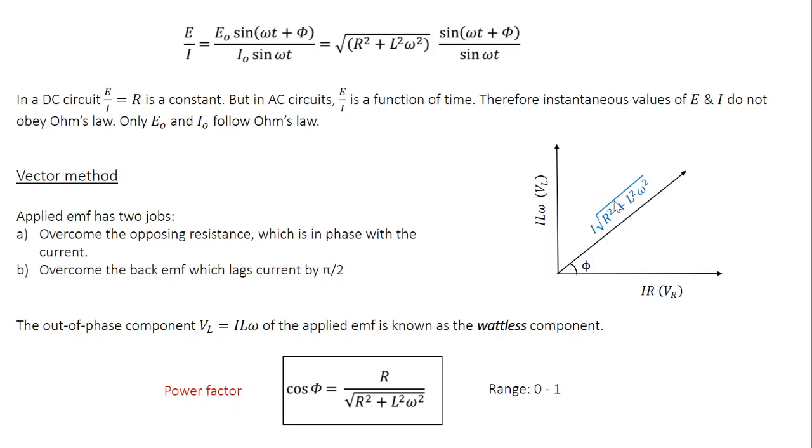Also, in the previous class, when we discussed AC flow through an inductor, I said that if you look at the waveform and analyze successive quarter cycles, you will see that in one quarter cycle power is positive and in the next quarter cycle power is negative. So the power is continuously transferred between the source and the inductor, and if you make sure that the internal resistance of the inductor is negligible, then you can switch power between source and inductor without any power loss.